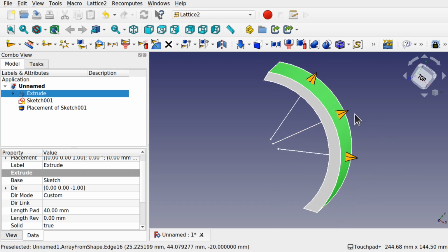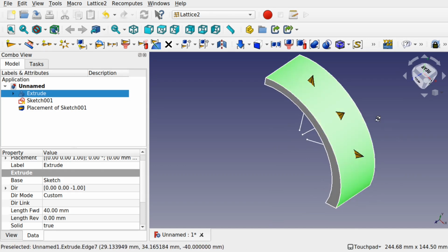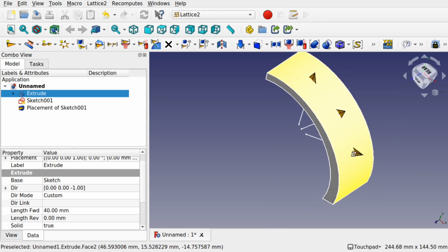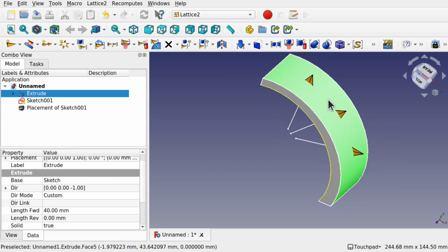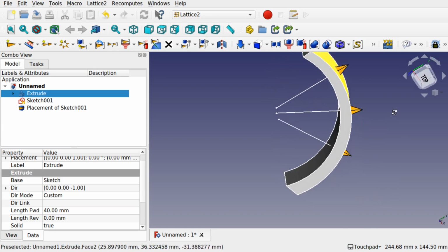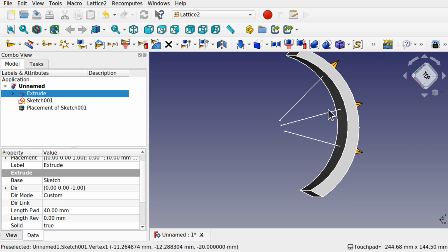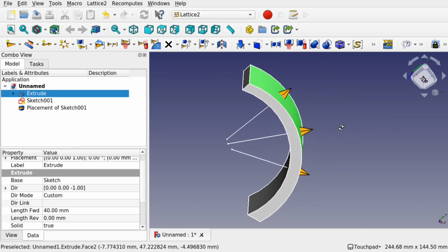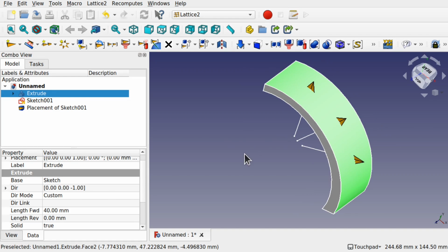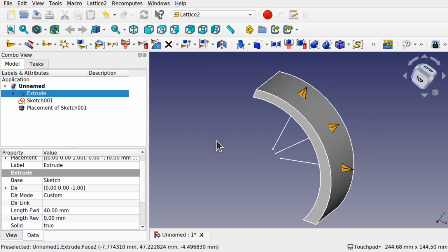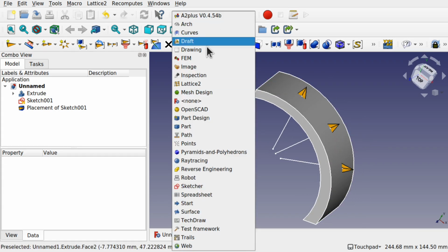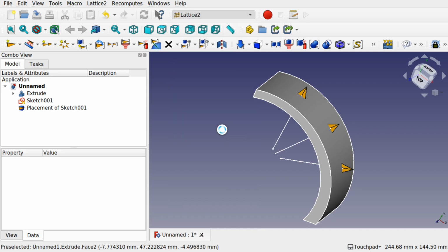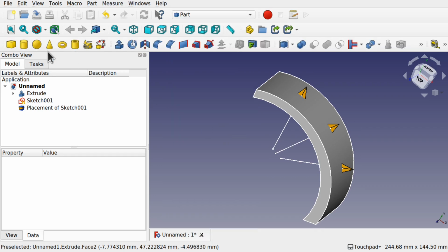So I'm going to place a cylinder along these. So I want to take holes out of these, and those holes are going to be tangent. If I try to place, say, a hole this way without having these at an angle, then we'll get a hole that just doesn't look right. It looks like it's just been drilled through on a straight angle. So we'll add a cylinder over in the part. Click on cylinder.